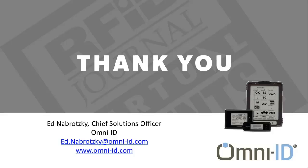Over the passive, we have a template built in, or templates can be downloaded into these visual tags. The template kind of decides how you're going to render the image. And so if you write a bit code with the passive tag, just through a standard RFID write, you write to a register to the passive part of the tag. It's electrically connected with a serial bus to the active processor. And the HTML schema that's inside can fill in that template and display the image. So that's kind of how you do it through a passive. On the active, you can send bitmaps if you want to, or you can use the same HTML template format. But if you're going through passive, you just write a bit code.